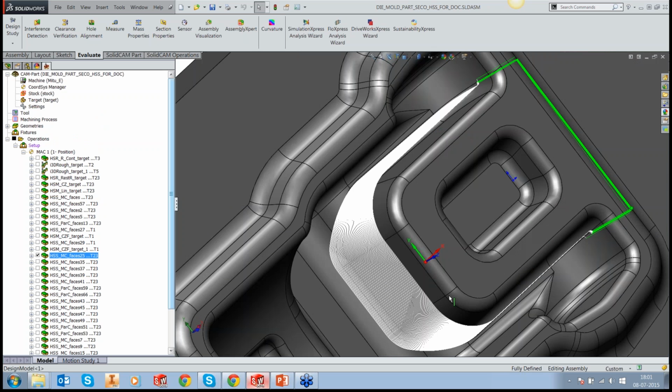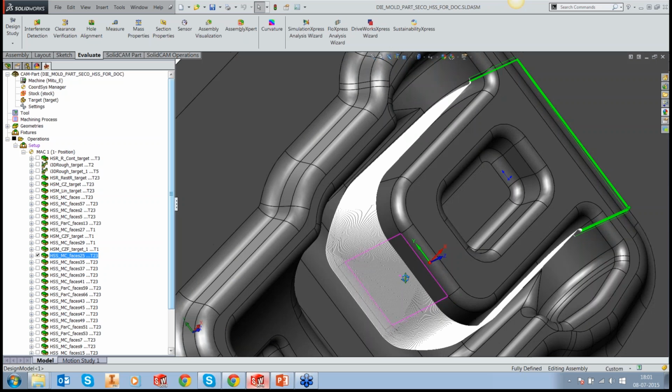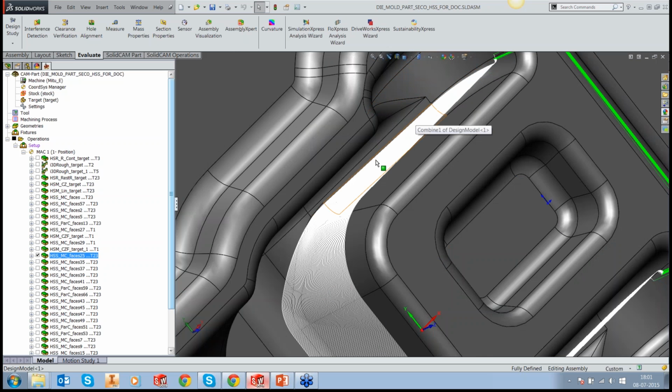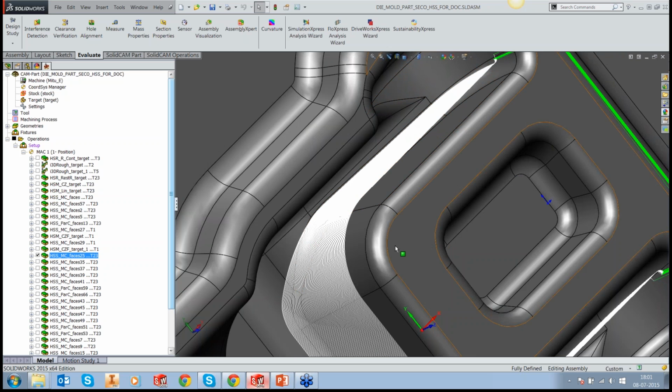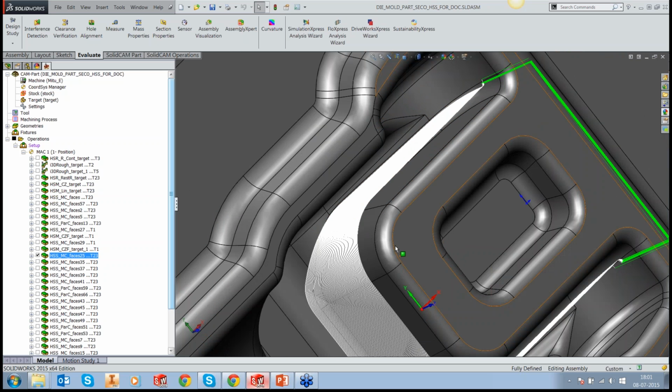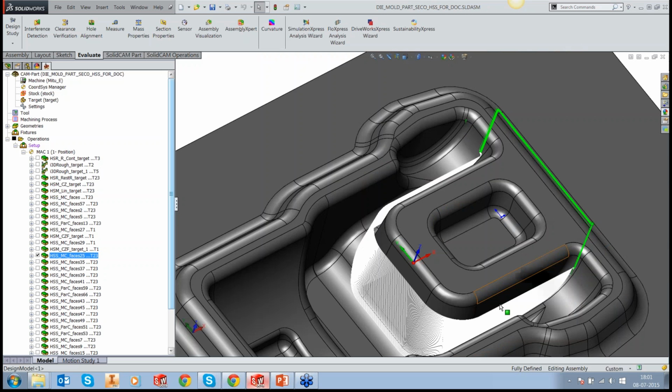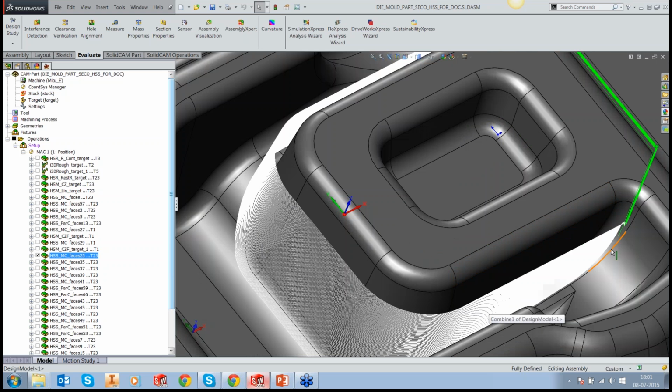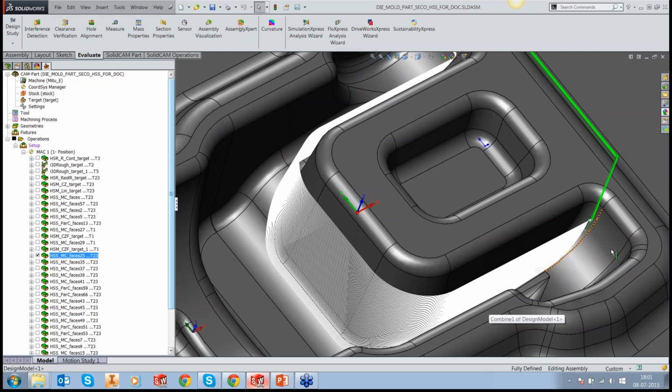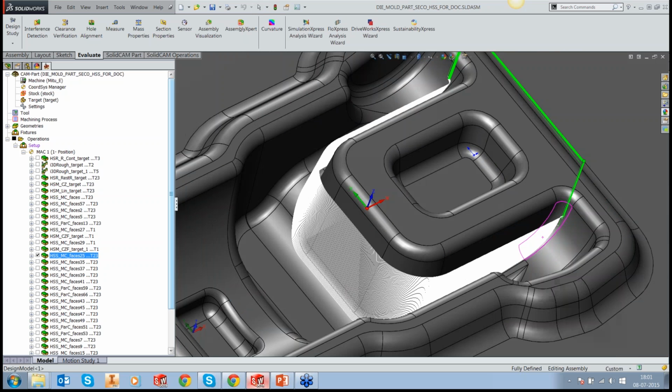single toolpath. And by doing it, we actually avoided that problem, which I showed you, because this toolpath has got nothing to do with the other wall. This is only cutting this wall. And it's cutting using the two curves. We morphed it between two curves. And we did one-way machining. So the surface, again, was excellent.